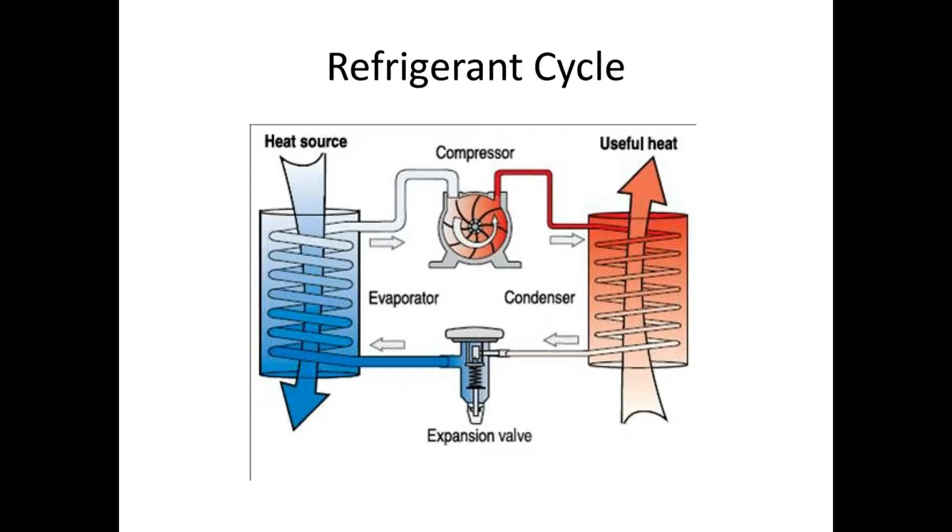But the proper way to say that is it absorbs an enormous amount of heat. So when the air is moving through the air handler, through that coil, it makes the air very cold, but what it's really doing is removing the heat out of the air in your house. Okay, and then that's how the cold air comes out the other side. So after that happens, it sends the refrigerant gas through the pipes back to the condensing unit outside, and the whole process starts over again.